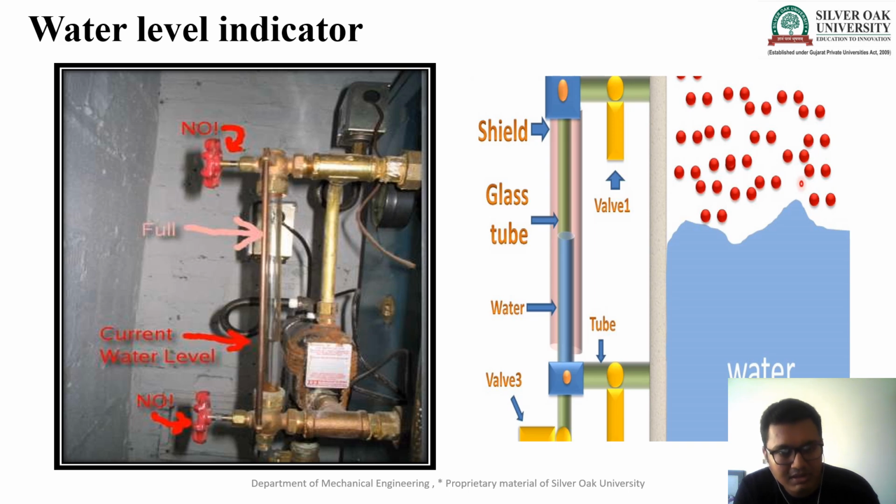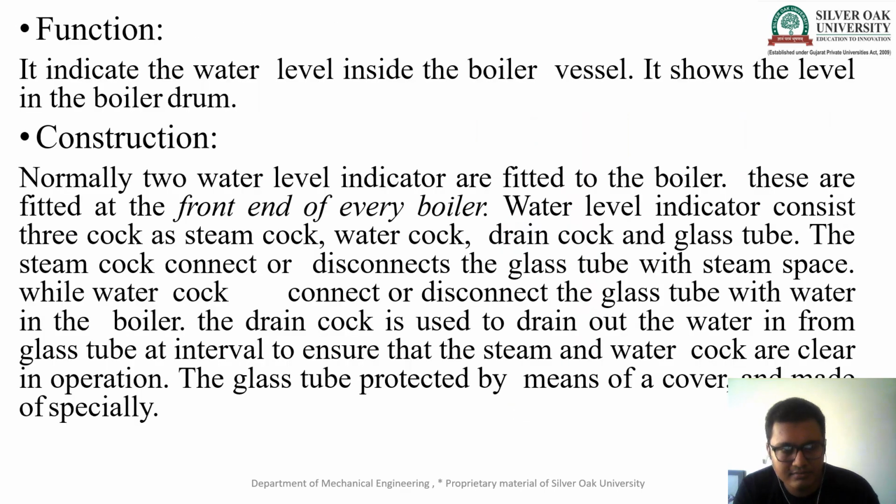It is compulsory that we know how much water is present inside the boiler, because if water is not available and we supply heat energy to the boiler, then the boiler gets overheated, and after overheating an explosion may occur. That's why we have to know how much water is present inside the boiler. Now, function and construction of the boiler, let me go through it.